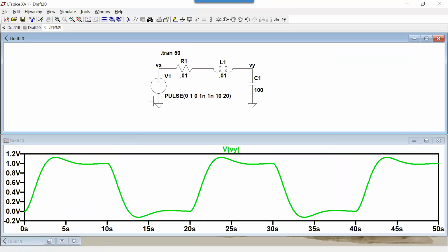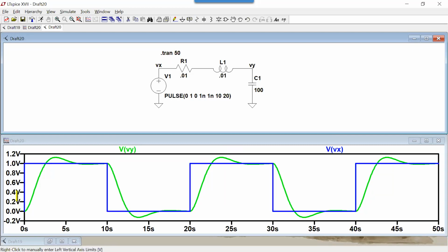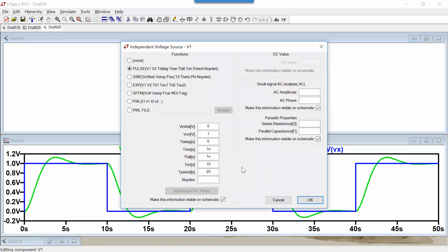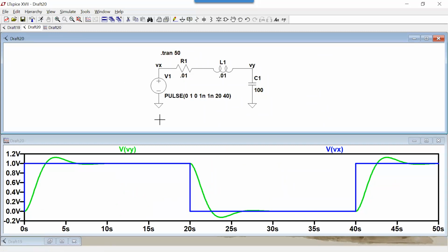And what you can see is that I have more than one pulse going on, that it goes on, and you can see it overshoots and then undershoots. And in fact, it hasn't quite stopped ringing. So I'm just going to make it 20. So really, because of the overshoot, yeah, 5 seconds, it's certainly over 1, but it takes a while for it to settle, right? But you can see that maybe in this case at about 10, it's finally settled down, all right?